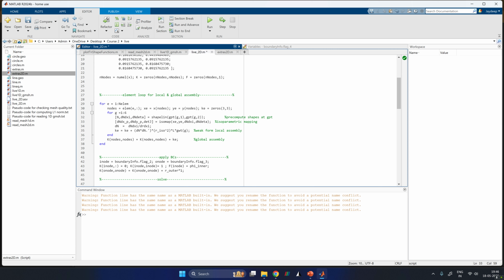and so now we have our physical derivatives. We can also just rename them simply as dn dx. Okay. Alright, so dn dx into dn dx transpose. So this is the first outer product in the x direction. So for our second order derivative in the x direction, and this is the y direction. Let's remove the radius term, and this will be determinant of j, and I think everything else should be the same.